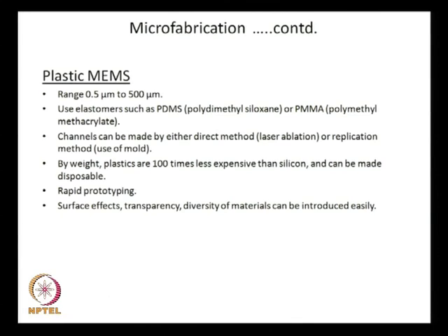Of course, there are negative points, nothing comes free. With plastic, there is a problem of aging. Glass will stand the test of time, but plastic may age after some time. And if you want to make something which has a high aspect ratio, that means a very thin but very deep channel, it is possible that when you press it, the channel may not maintain its aspect ratio. So, there are issues on the other side of the balance as well.